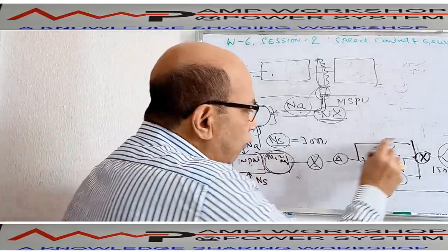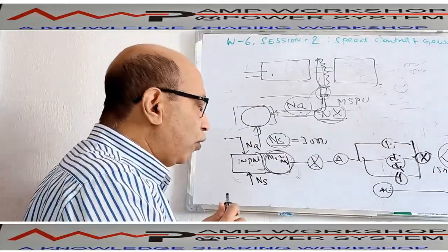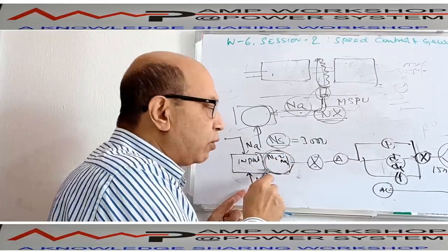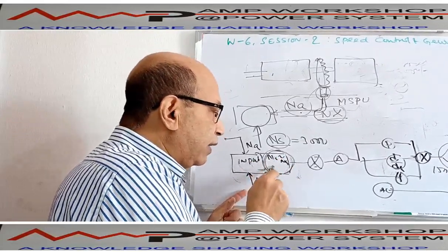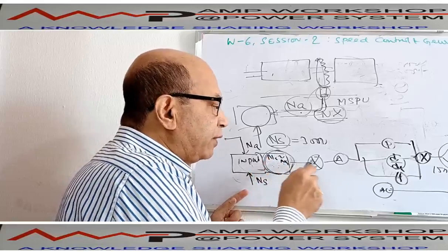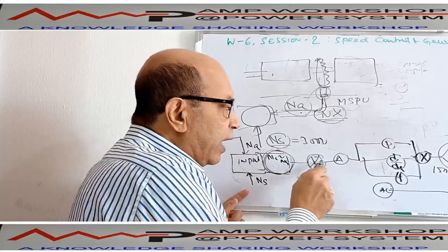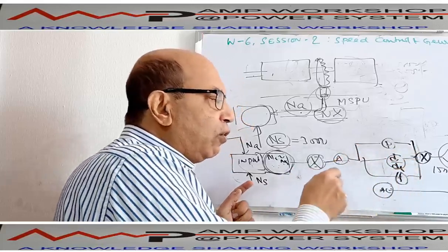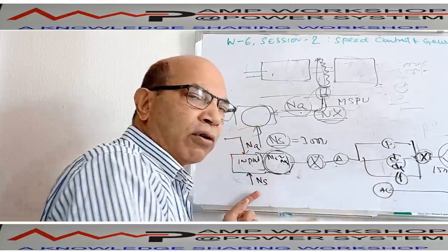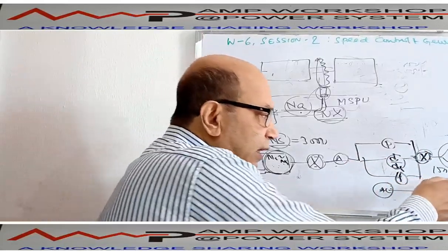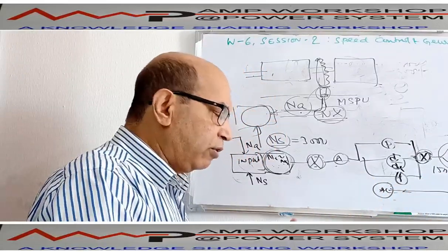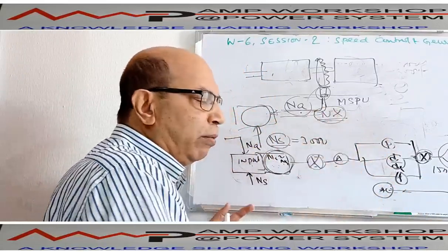This way the control loop is operating. How? There will be an input section in the controller. The controller will take this input signal and the reference signal and take the difference. An error signal will be generated, and control action will be applied on the error signal. Then the final control signal will be generated. The control signal will be amplified and filtered, and then this final signal will come to the actuator. This way the control loop operates.